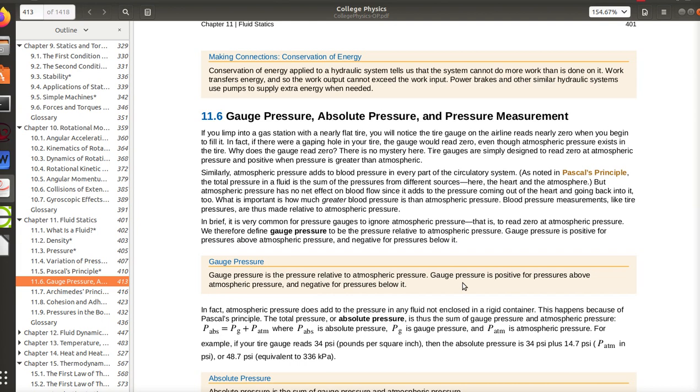And that's just because of the way the spring is set up to go to 0. But what we know is that gauge pressure, anywhere on the earth, we have 14.7 psi of atmospheric pressure from the weight. Well, at sea level we have 14.7. The higher in elevation you go, it goes down a little bit, but it doesn't go down a great deal. So gauge pressure is what your gauge reads, and it's in reference to, it's not counting the atmospheric pressure.